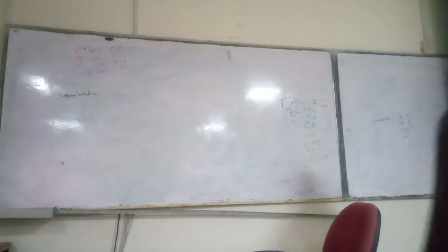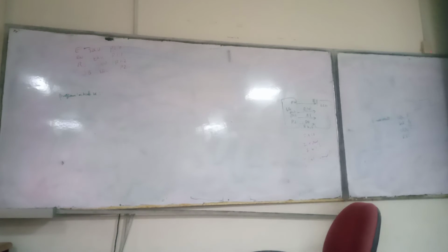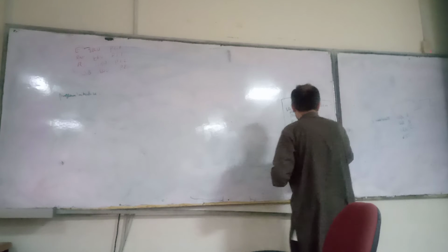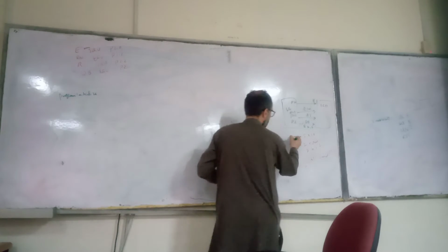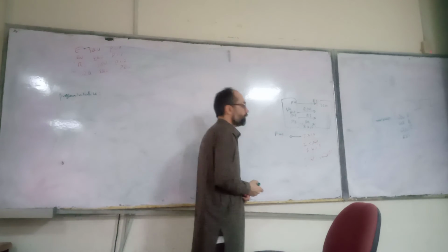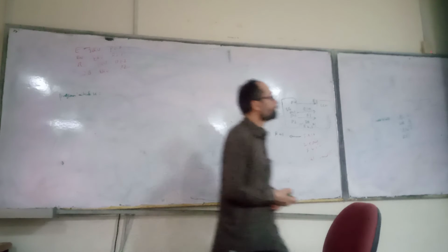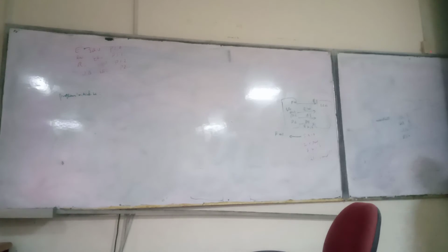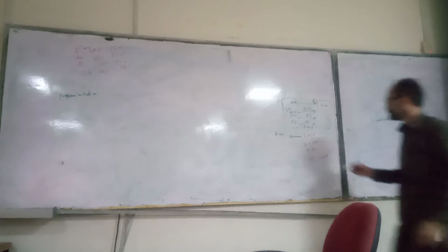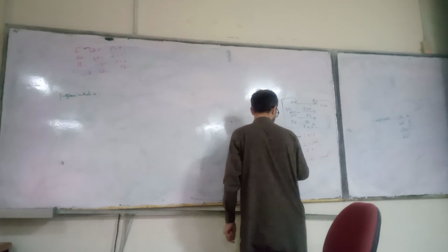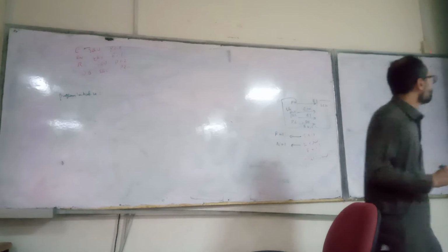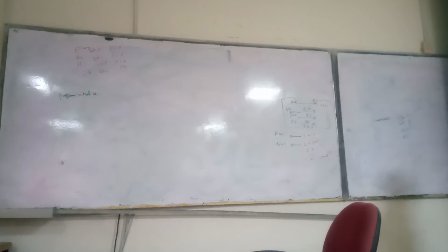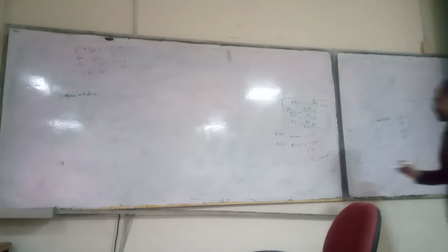Okay, now if you look here, if you want a 5 cross 7 standard display, what should be the value of F? F should be 1. If you want to initialize it in the 2-row mode, N should be 1. And if you want 8-bit, DL should be 1. DL, where is DL? DL should be 1.